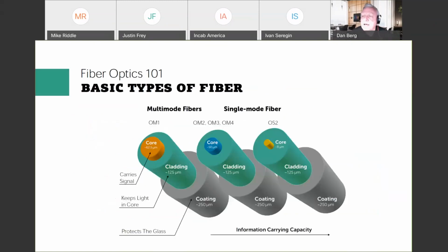Oh, okay, we're getting into stuff that I better understand. These are the basic types of optical fibers that we use every day in our industry. They vary in size, they vary in capabilities, and they're for certain applications in the field. The 62.5 is a relatively new fiber type. It is primarily used for LANs, where they don't need huge capacity. It's easier to handle in the field. It takes a wide range of sources, and it takes some mechanical connectors as well.